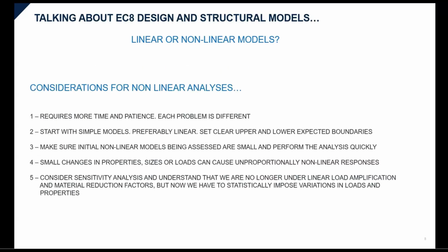We must also provide some very clear ideas about the types of considerations we must make when performing nonlinear calculations. First, nonlinear analysis consumes much more time and patience. Each problem is a different problem. We should always start with very simple models, preferably linear ones. Clearly define a lower and upper range of expected results, and preferably ensure that our initial nonlinear models are quite small and can be calculated fairly quickly.